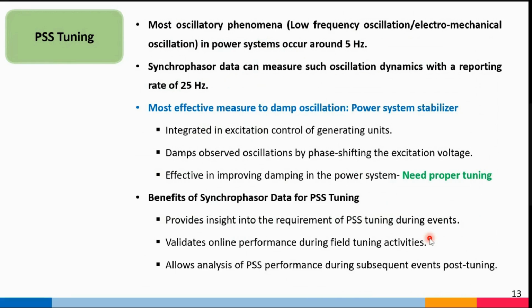But with PMUs at a 25 hertz reporting rate, you are now able to monitor this oscillation in real time. And not only the monitoring is important, what corrective action is required for damping of this oscillation is very important.